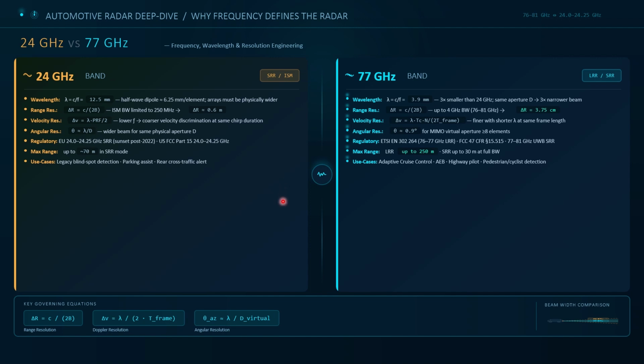Whenever we talk about automotive radar, we hear a frequency of 77. And we used to hear another frequency band which is 24. Now you will wonder where these numbers are coming from. Basically, this frequency band is dedicated by the FCC, the committee that governs the frequency allocation, or ITU in Europe. They're the ones who allocated this band for automotive radar. 24 used to be there, but it's phasing out because there are some advantages of 77 gigs.